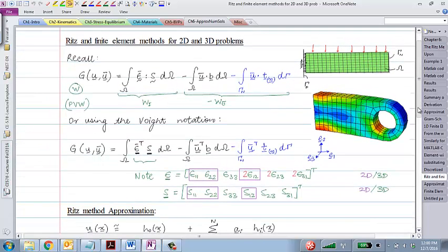So what we'll do is we'll make approximations just like we did for 1D problem. We'll say that real or virtual strain will be written in this vectorial format first of all. E11, E22, E33, and so on, these are the 6 symmetric components of the strain tensor, right?